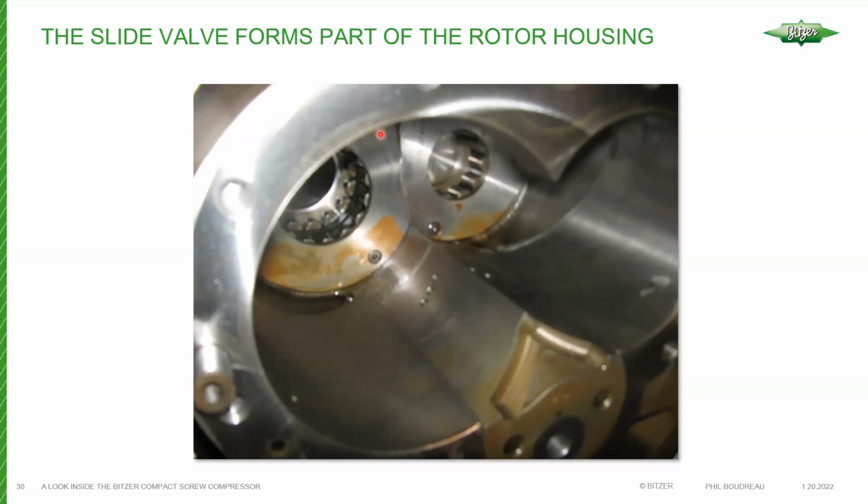By the way, these are those suction spacers I was talking about. If your rotors move too far to the back, they're just going to start cutting into the suction spacers and making a mess. And well, let's just say at that point, it's pretty much game over, because once you start making metal inside that compressor and the rotors start picking it up, it's just going to start basically chewing everything up.